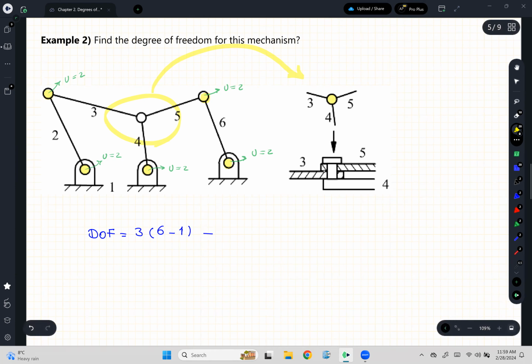You see, this is the joint there. So link 3 is being sandwiched between link 4 and 5, right? So you can think about it and visualize it. Maybe this pin is being attached to link 4, and 3 and 5 just have a hole in them and they can rotate. Try to visualize these connections. This is how three members are connected at one point.